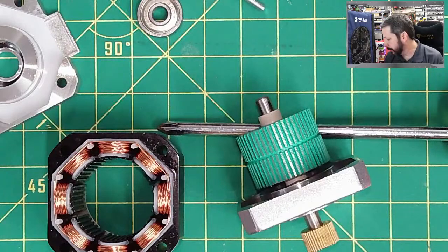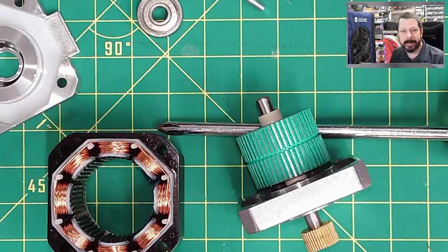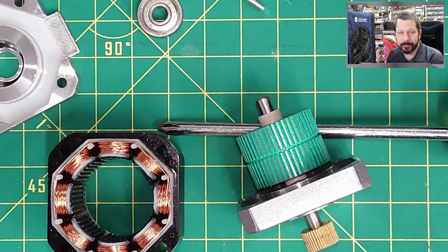The problem with micro stepping is that, yes, you can get the partial steps, but every time you go down to another level of micro step, you lose some of your torque, that holding power torque. So if you need this to generate torque or hold a position, and you're doing extreme micro stepping beyond like 16th or 32nd stepping, then it's not going to have as much holding power and not as much torque. So that's a downside to what you gain from the resolution.